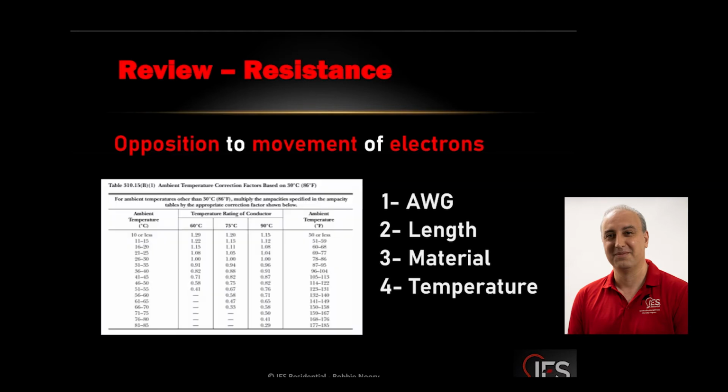And you'll see this when you do your wireman test. I'm pretty sure George does some problems for you on this table. This is what we call the ambient temperature correction factor. So normal ambient temperature in most US cities is 78 to 86 degrees. Houston, San Antonio, Phoenix, they all fall under this. Northern cities too. This is a pretty wide range. This is the average for the whole year.